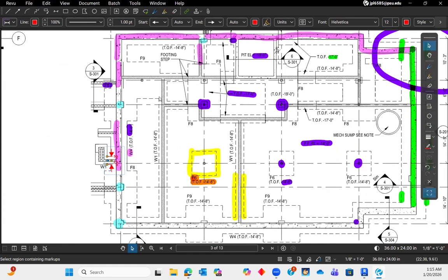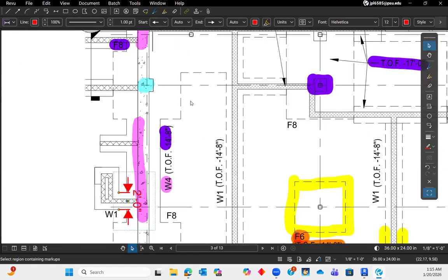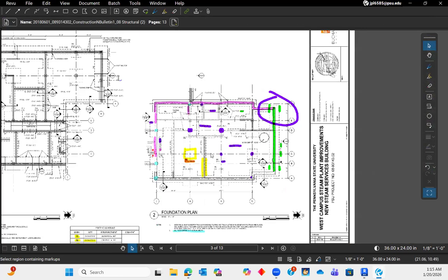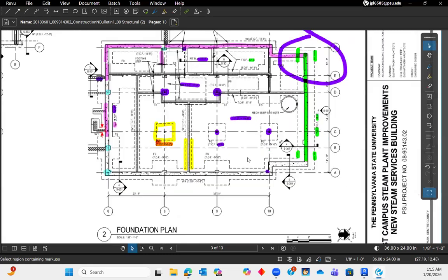And another thing, for the location of these walls, we allow you to just measure on Revit for all the location of these interior walls, because sometimes they don't line up exactly with the architectural drawings. So you can just do a quick approximate measure on Bluebeam for those location of these interior walls.